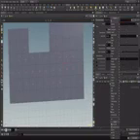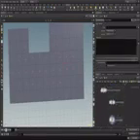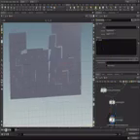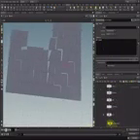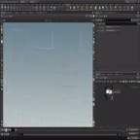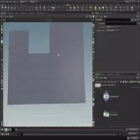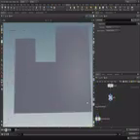So let's place down the point wrangle. We're going to look at our initial rest position. So @B = @rest; and close it. There we go. As you can see, it's not working perfectly yet. So that was the rest position we were getting from this node over here. But it's not working perfectly yet. And that's because it's subdividing it into squares, but it's subdividing this large polygon and it doesn't know where to get the value from exactly at this moment.